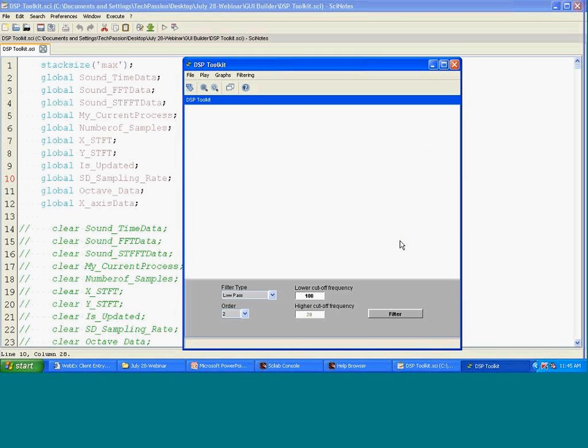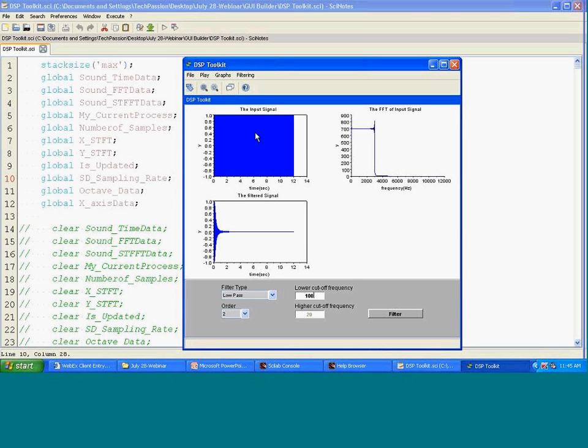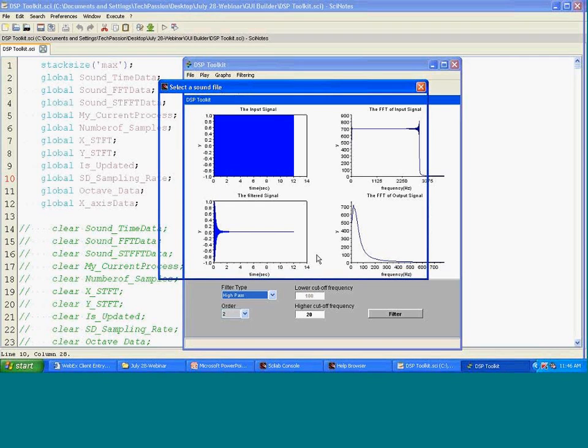So this is the view, and now in the next view you'll get 4 plots. This is the time signal we started with, this is the FFT of the signal. I've done some filtering, so the higher frequencies should go away. This is what you observe here. Initially I have frequencies up to 4000 Hz or so, whereas after filtering, since I set a lower cutoff of 100, it is starting to roll off, which is reflected in the time series. The original chirp signal versus what I get after filtering are quite different. There are other options. You can have drop-down menus, you can add radio buttons, you can have slider bars, and so on.